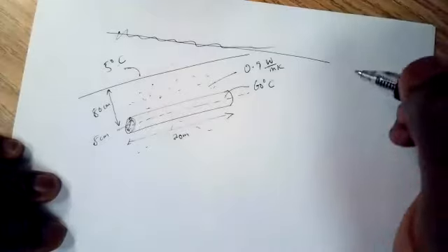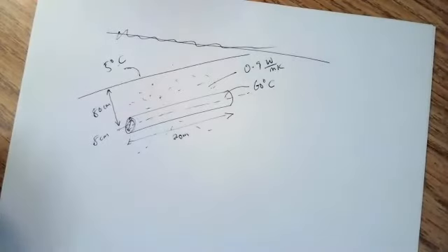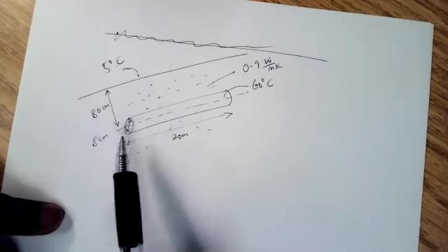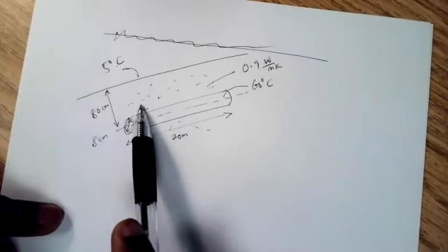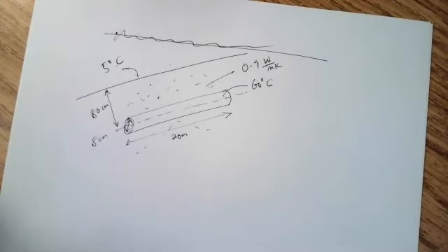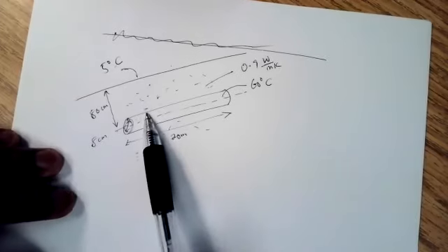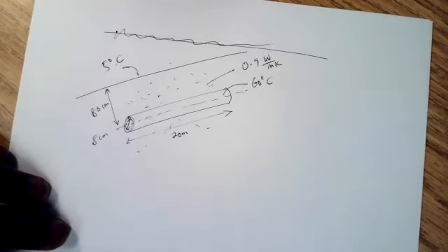And if you remember, when we were talking about the types of axis of analysis, we talked about cylindrical coordinates, spherical coordinates, and then Cartesian. So heat is going to be lost from the pipe to the ground. To analyze that properly, you have to use cylindrical coordinates, and then assume that the heat loss in the ground will be your regular Cartesian coordinates.